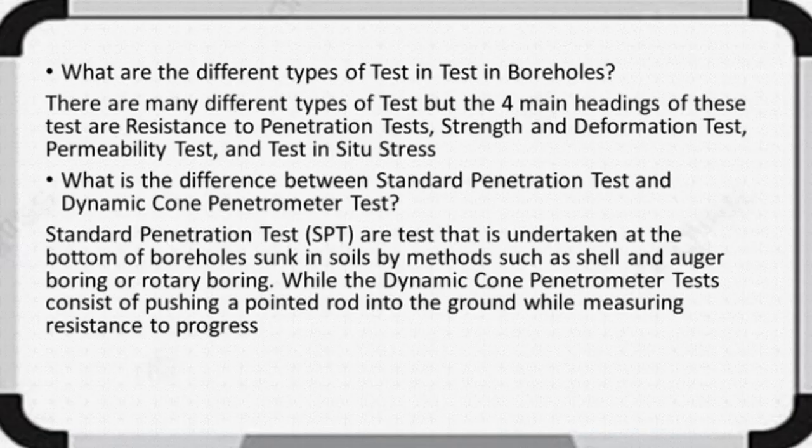So number 3: what are the different types of tests in boreholes? There are many different types of tests, but there are four main headings of these tests. These tests are resistance to penetration test, strength and deformation test, permeability test, and test in situ stress.